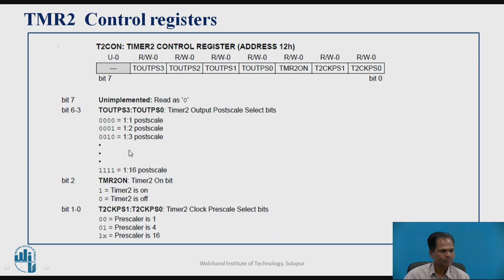Now this figure shows the bit format for the control register of timer 2, T2CON. So bit 7 is not implemented, undefined.